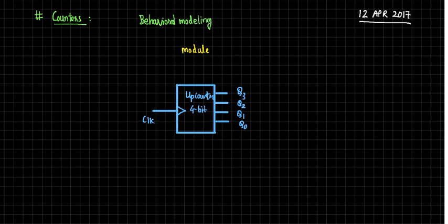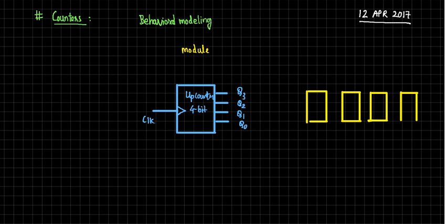In the structural design, we would have 4 such flip-flops connected one after the other. You know this design, right? How would the structure be inside this? 4 flip-flops. Which flip-flops? Any flip-flop operating in toggle mode. Just because it's positive edge triggered, we'll have a... Now again, the counter may be synchronous or asynchronous. Here we will go for a ripple counter.